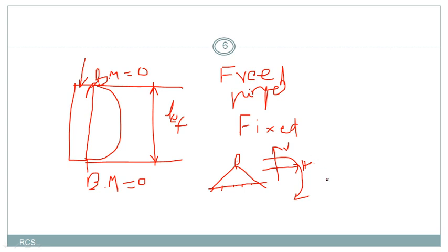That means there we have restraint, meaning resistance of movement in the x direction, or I can say horizontal direction, and the vertical direction, and there is no resistance to rotation of the door in the clockwise or anti-clockwise direction by means of providing a hinge support at a particular location of the door. So if you provide a hinge support at any one end of the column, it is free to rotate. They can rotate clockwise or anti-clockwise when you apply the load over the column, right?